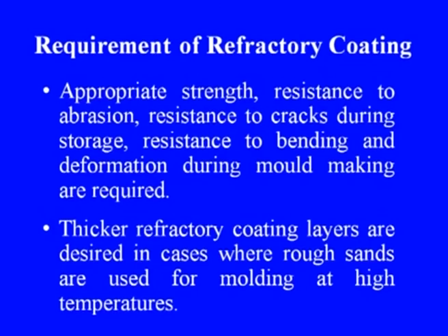Quick drying is preferred. Coating should get easily stuck to the pattern and there should be provision of controlling and adjusting coating layer thickness. Appropriate strength, resistance to abrasion, resistance to cracks during storage, resistance to bending and deformation during mold making are required. Thicker refractory coating layers are desired in cases where rough sands are used for molding at high temperatures.